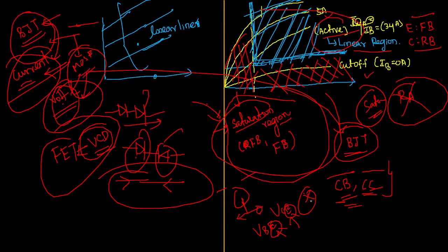இப்போ derivation point of view, there are something we need to verify. நீங்க ப்ராப்ளம் சால்வ் பண்ணும்போது என்ன பண்ணணும் அப்படின்னா, people used to give something. Sir, some things I'm just recapturing here. While solving the problem, I will be bringing other things. Okay, one minute. It is stucking. Yes. How to identify the region of operation? That is one more thing. What is this region of operation? Whether your transistor will be in cutoff region or your transistor will be in active region. I told we are going to keep our attention with the three region: cutoff region, active region, and or your transistor will be in saturation region.